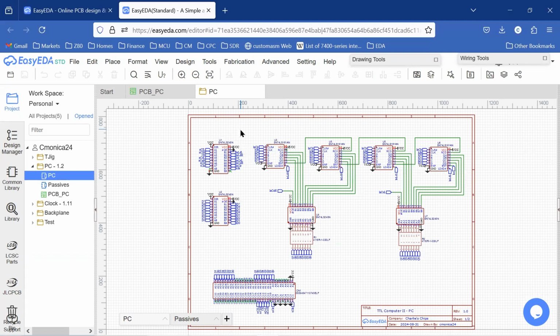So we have two 74LS245s that buffer our input for our control signals and for our data bus, and drive the local signals on our card. And we have our four 74LS161 counter ICs. We have these two implementing the high byte of the program counter, and these two implementing the low order byte of the program counter.